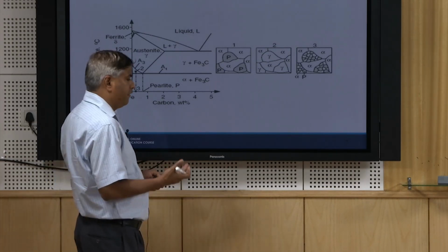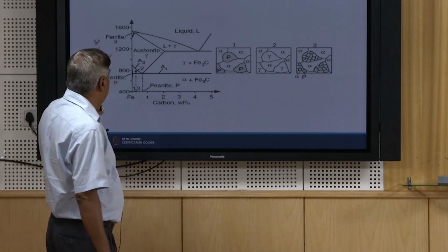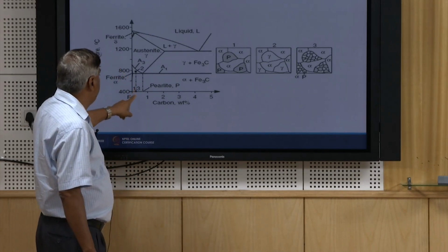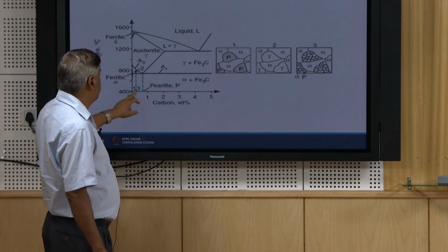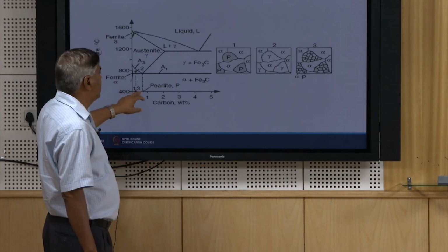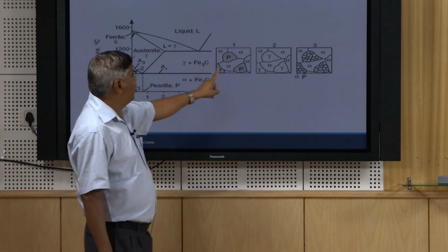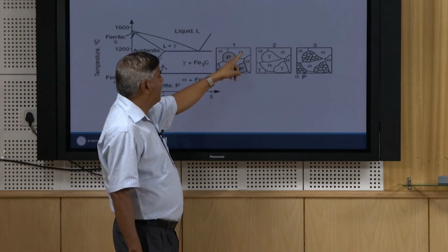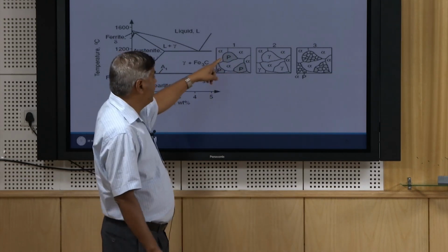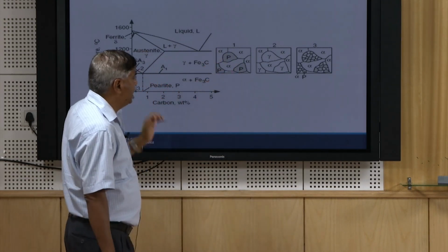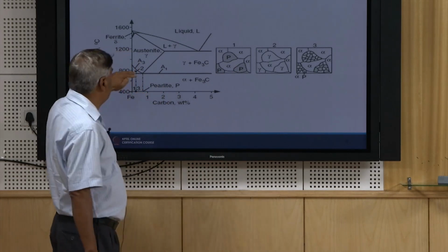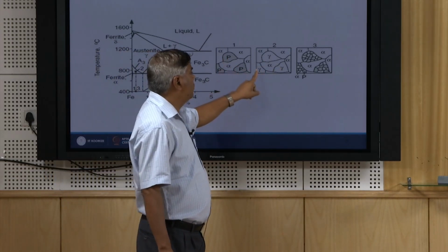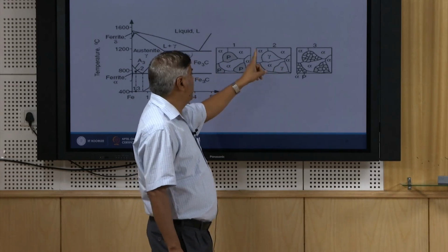As per the composition, it will have different phases. If you look at the base metal, say a typical steel corresponding to 0.3% carbon steel, at point 1 it has ferrite and pearlite. The ferrite alpha and pearlite are the grey shaded areas. When it is heated to point 2, the pearlite will transform into austenite, while the alpha will remain as it is.